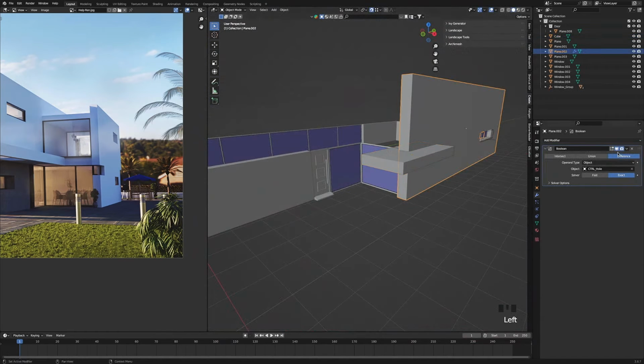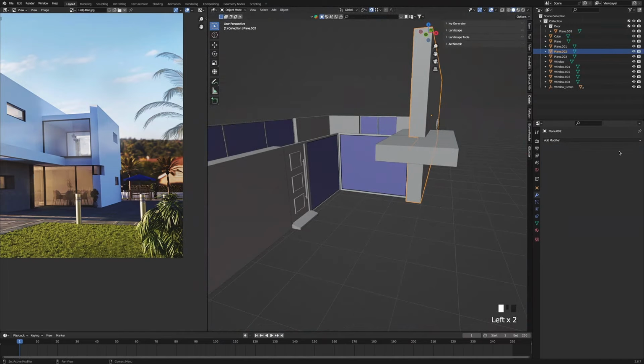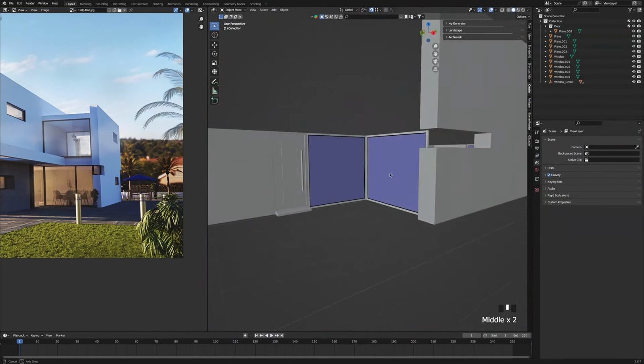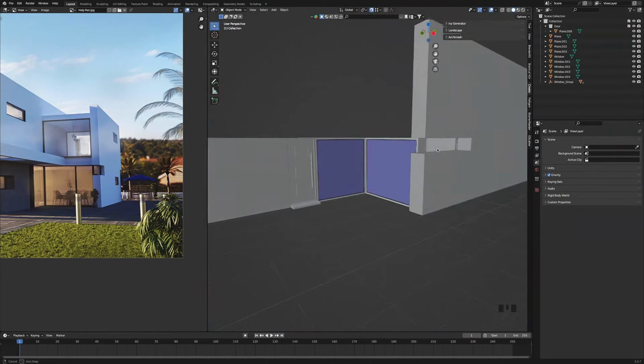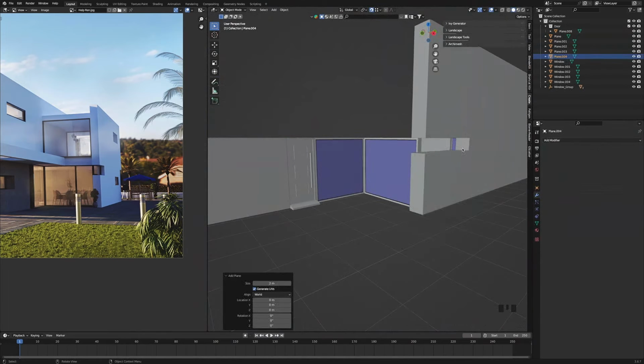We're going to select the wall. I'm going to go over here. We're going to duplicate the Boolean, but then we're going to click the X to get rid of the empty, and we're going to click the eyedrop tool and select the cube instead. And now we're going to apply both modifiers. So now if we select the cube and press X and delete it, our cutout stays there even with the cube gone.